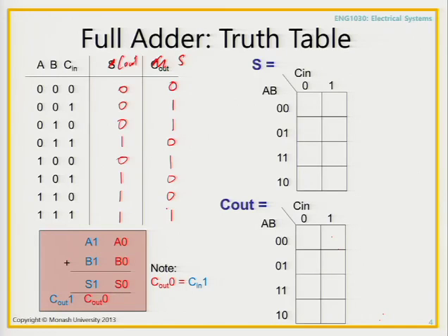Now, described behaviors can get pretty complicated. Anything that you can think of, any way you want a system to behave, can be captured using a truth table. Okay? So now we go about minimizing the logic for this. We put it into our Karnaugh map. For the sum, we would put 0, 1, and I'm going to go a little bit faster because I can, 1, 0, 0, 1. Right? So that would be the Karnaugh map for the S output for this truth table.